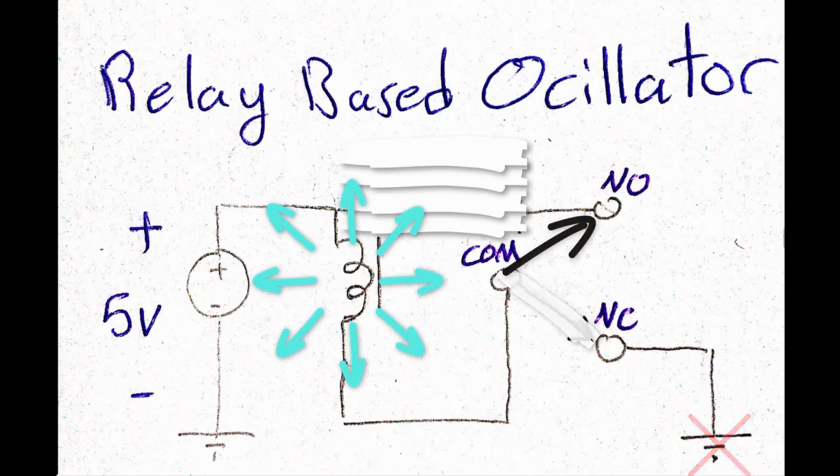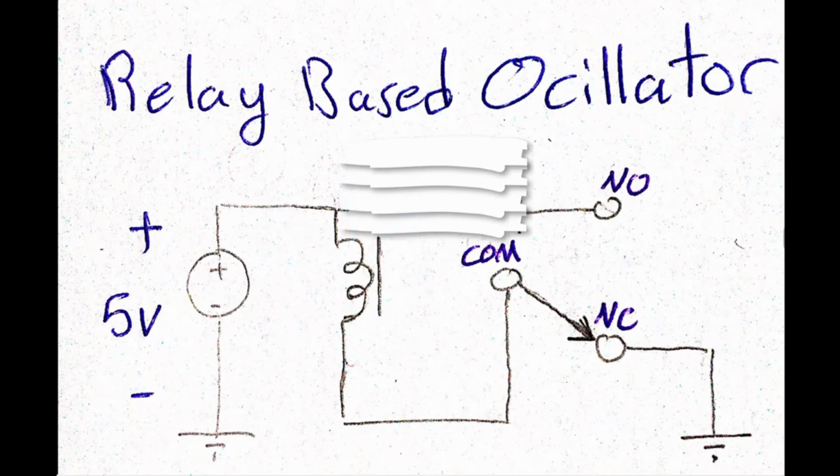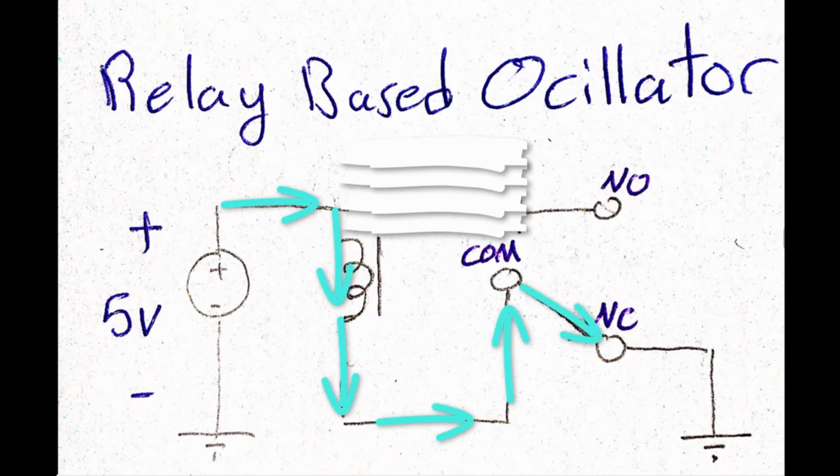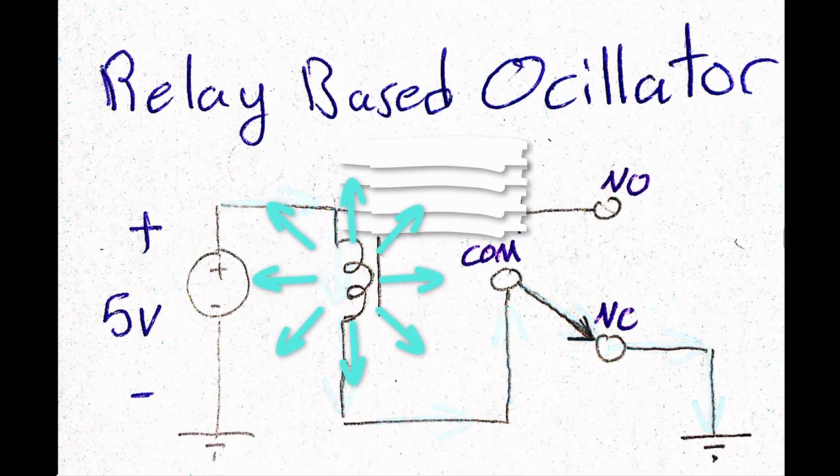This will lead the relay switch to return to its normal state when the relay coil loses its energy. But this is not the end yet, since now the circuit is connected to ground, which means that the relay will be energized and the relay switch will change its state again. This process will go on forever as long as there is potential difference across the relay coil.